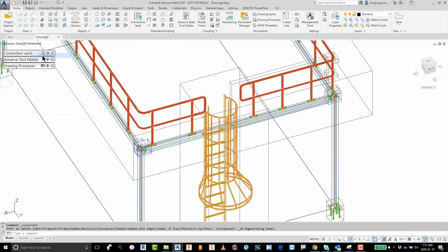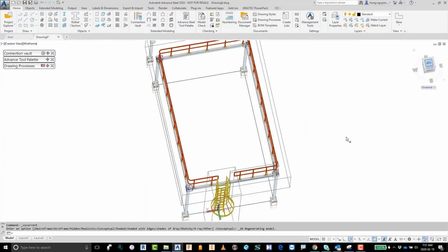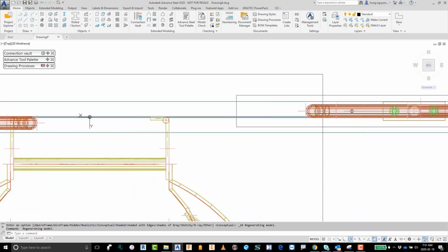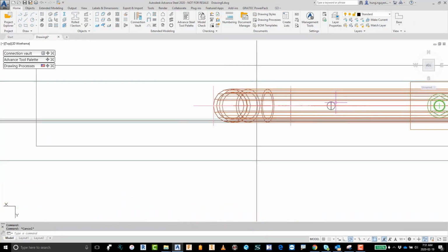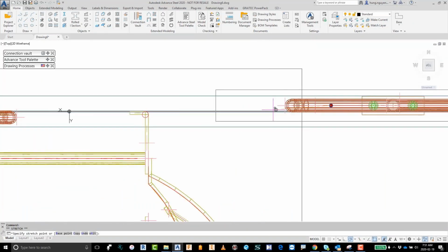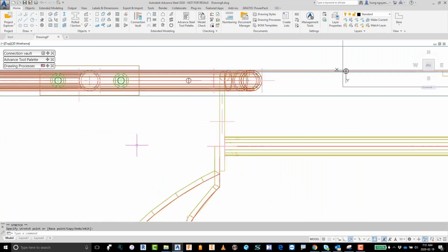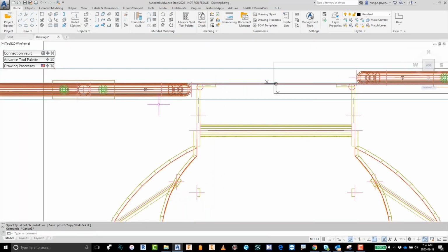So how am I going to resize the handrail to the proper position? You see, when you put in the two handrails, they have two dots in there, and it's very clever. So I like the handrail to move and lengthen closer to the cage, so that there's no gap in between. All you need to do is pick those two dots on the handrail and drag them. I drag it backward to the left, so it will not jam into the cage of the ladder. So I just simply manipulate it, or if you like, you can enter an exact number to configure it that way.